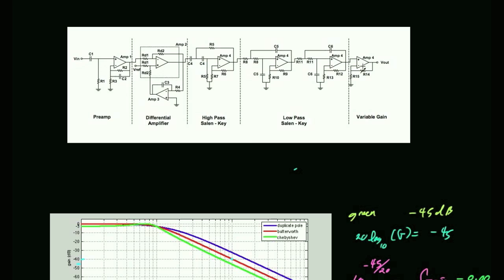But the point is, you have all the tools to understand this circuit. If you understand how to do the math for each stage, you can daisy chain them together all day long and just make sufficiently more sophisticated circuits. So this is a circuit that's got low pass filters, high pass filters, and gain. It's basically a band pass filter with gain. So I amplify the frequencies of interest to me, and I filter off the frequencies that are not of interest to me, and hopefully the signal that I've got left is exactly what I want.